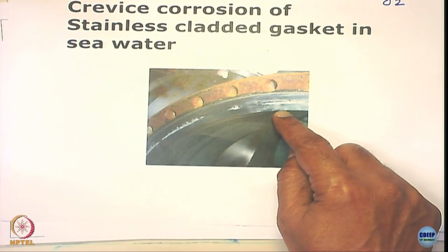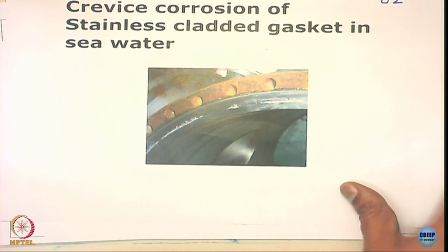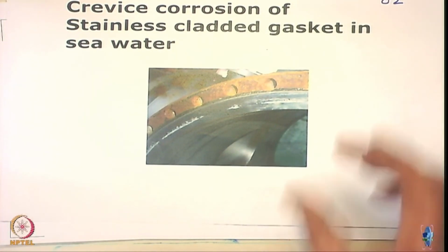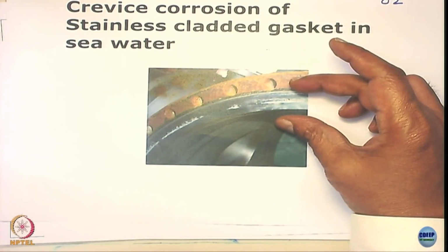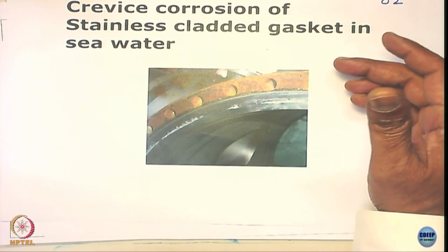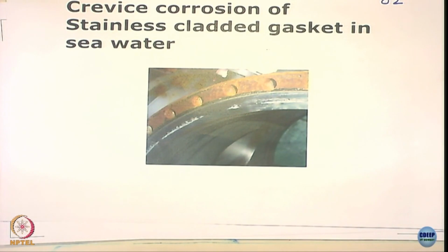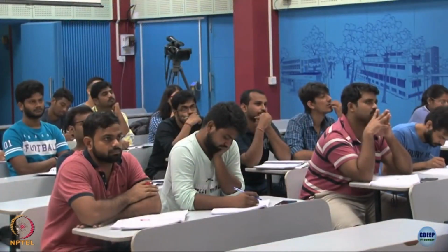You will see later when you talk about pitting corrosion, this duplex stainless steel has got high resistance to pitting corrosion. And you clad it because you can't use the whole thickness of duplex stainless steel, it is expensive, right? You just go for a 3 millimeter clad because the basic carbon steel is cheaper for us to do that. So that is about the